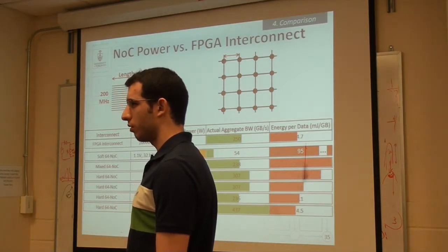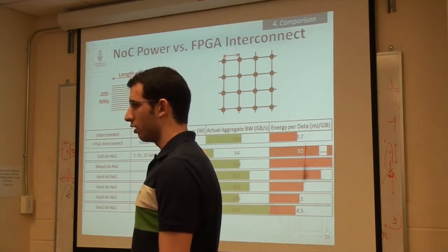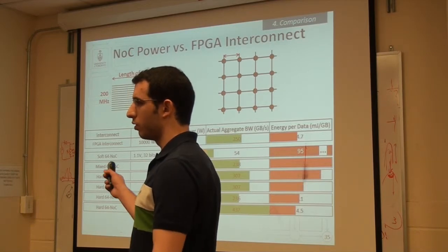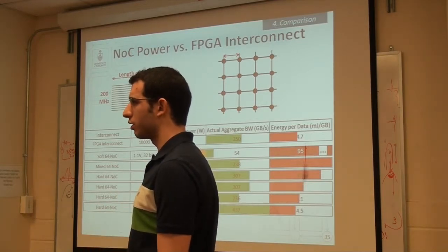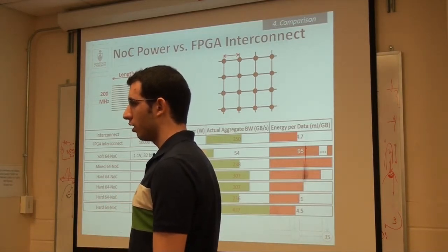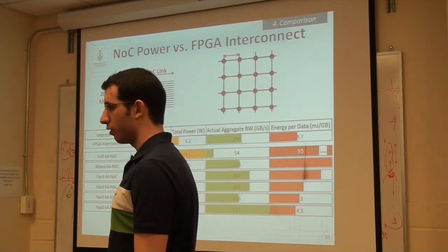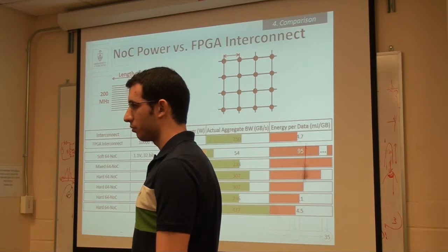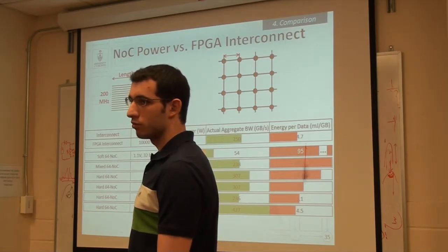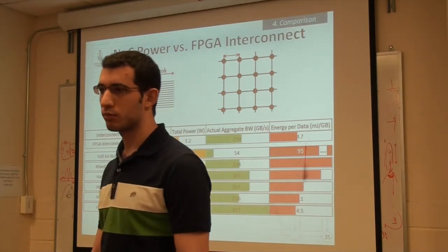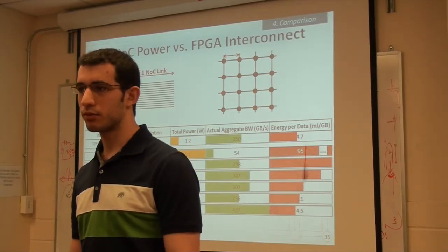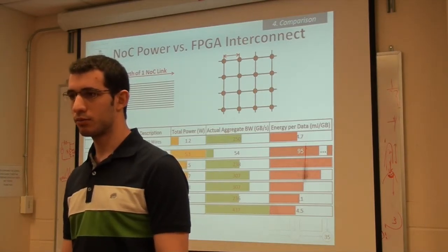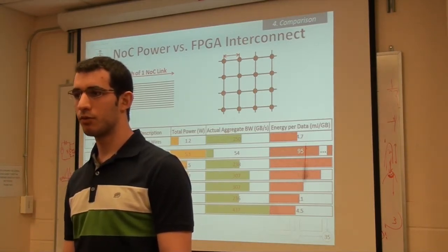So each router has 3 cycles, and at the endpoint, the fabric port will add another 3 cycles to that. At whose clock frequency? The network's or the user's? The network's. Well, 6 cycles at 900 megahertz. So you might want to, I know you've done simulations for that DDR system of latency for the QSys system versus the NOC. So what's the answer?